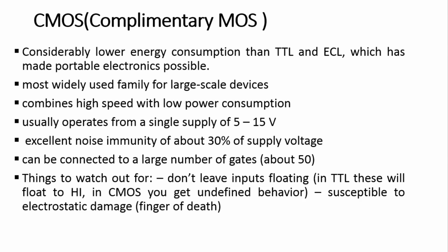Can be connected to a large number of gates, about 50. Things to watch out for: don't leave inputs floating in TTL. This will float to HI. In CMOS, you get undefined behavior, and the device is susceptible to electronic damage.